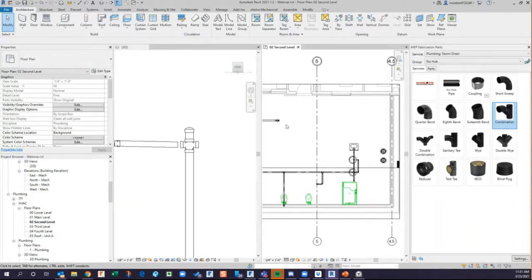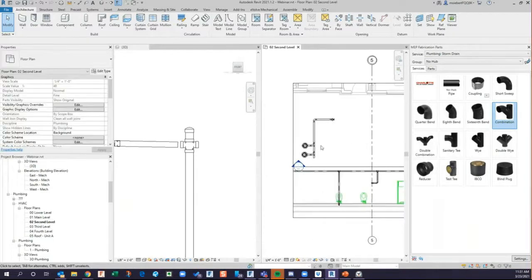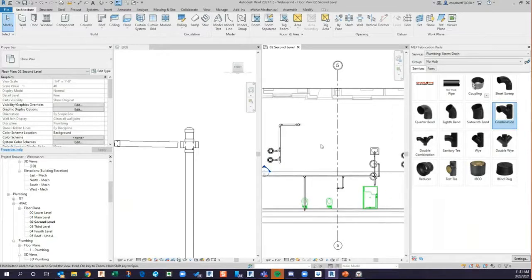Now I know I have a 3-inch pipe coming from this point and I'm going to be drawing it over here, but I'm going to do a little bit of value engineering on it. When I drew this out, I don't really like it being over here unless I have a hanger point. I might feel more comfortable if I have the room to put it right underneath the actual storm heads and just look right up into them.